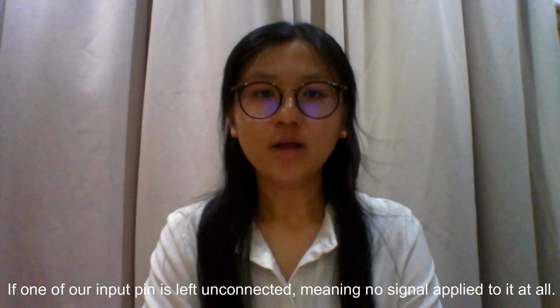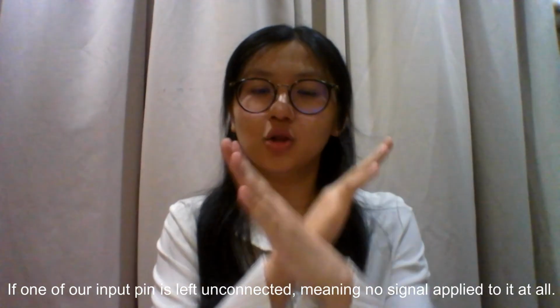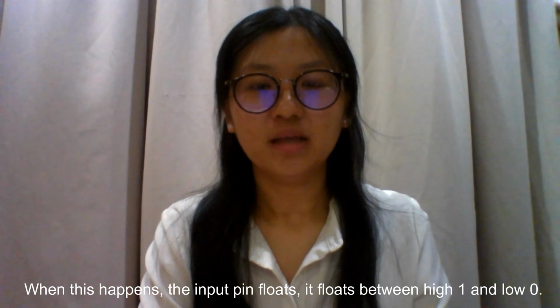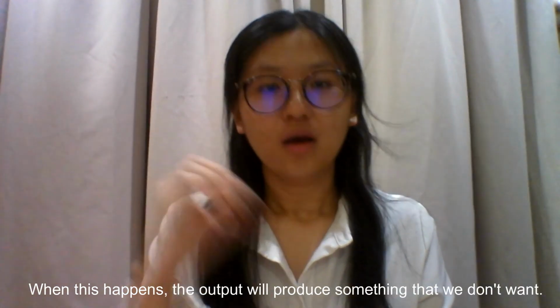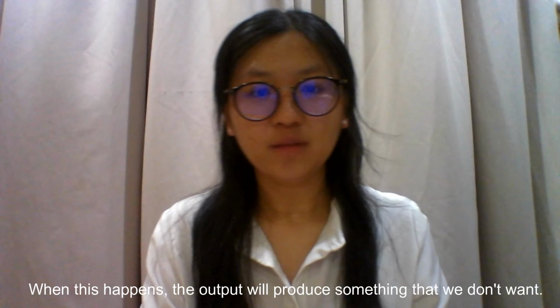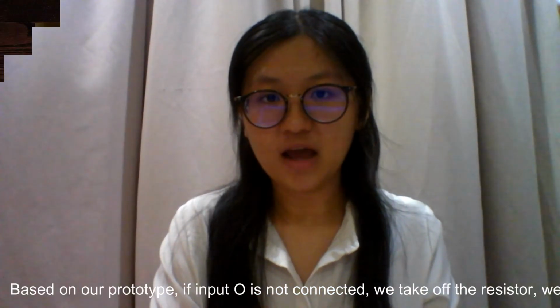If one of our input pins is left unconnected, meaning no signal is applied to it at all, the input pin floats. It floats between high, 1, and low, 0. When this happens, the output will produce something that we don't want. The output now becomes unreliable.